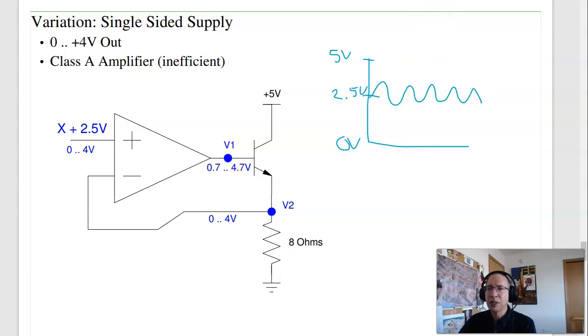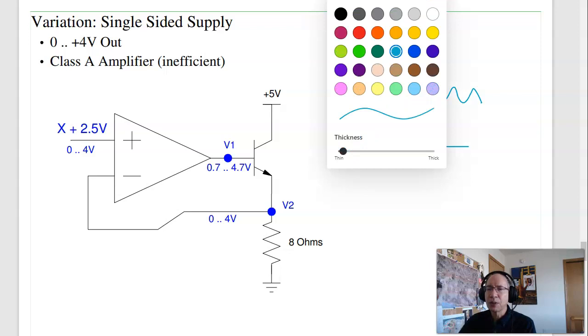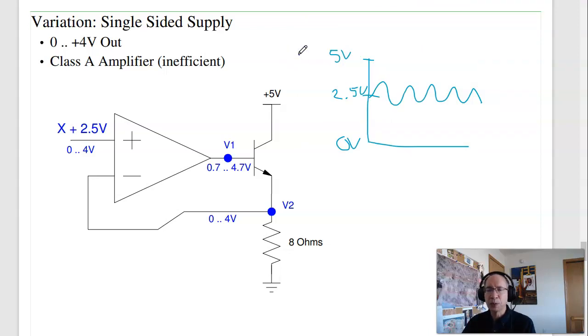0 is an arbitrary number. Think about birds on a high voltage line. They think 13,000 volts is ground. We think earth is ground. They're both perfectly valid. Just don't tie the two together. I could treat this as circuit ground, so that's 0 volts for the circuit. This behaves as minus 2.5 volts for the circuit, and plus 2.5 volts.